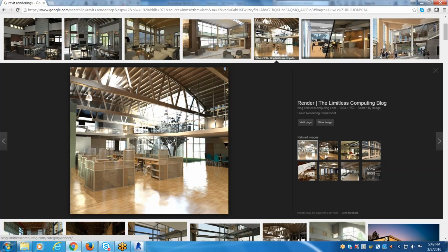You don't put the prongs in the outlet for DD issuances, right? All I need is something that functions correctly, meaning it hosts to anything I would tell it to, because there might be floor-mounted devices, there might be ceiling-mounted devices. So the duplex receptacle needs to be able to host all these things. It needs to have shape so that when I go into the 3D model, I see it there. And it needs to have the BIM information behind it: voltage, circuiting capabilities. It needs to have the right family category so that when I place it, we can do a quantity takeoff and say how many duplex receptacles are in this project. So all of that needs to be built into visible and non-visible information.